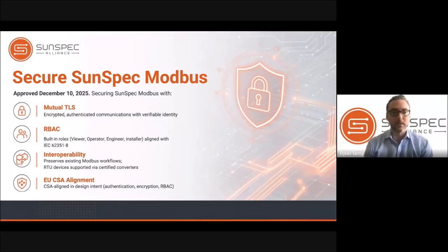Like I said, the implementation guide was approved on December 10th, 2025. It's based on the modbus.org Modbus TCP security specification that has existed for many years. And so we based the Secure SunSpec Modbus implementation guide on that previously existing standard, and also adapted some of the rules and regulations from outside regulations like the Cyber Resilience Act and the Cybersecurity Act in the EU to include things like the role-based access control to align with what is in IEC 62351-8.